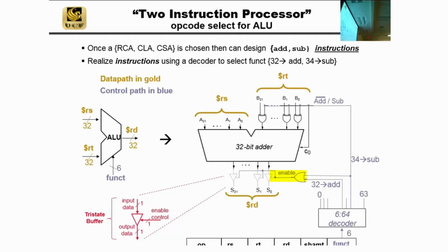They're just sitting there. But do they say a 0 or 1? Well, any choice they have is going to be wrong half the time. The only right choice that they could say is no comment, is high Z. So a little takeaway, this is an example of a bigger thing to keep in mind. Anytime we design hardware that has an output, you're connecting 2 outputs together.